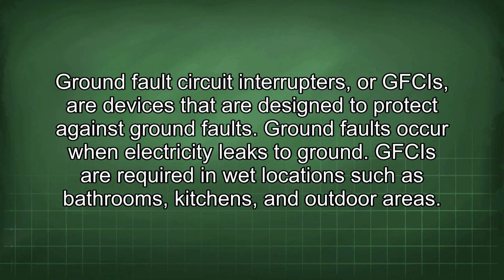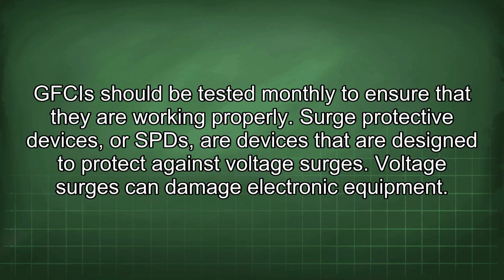Ground fault circuit interrupters, or GFCIs, are devices that are designed to protect against ground faults. Ground faults occur when electricity leaks to ground. GFCIs are required in wet locations such as bathrooms, kitchens, and outdoor areas. GFCIs should be tested monthly to ensure that they are working properly.